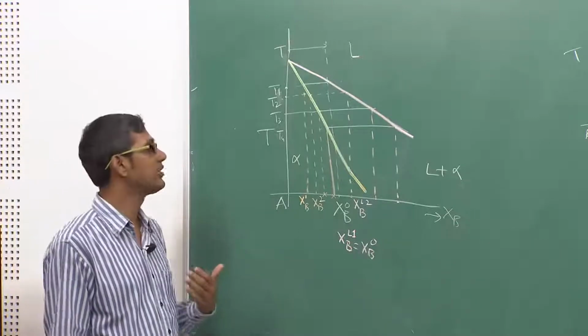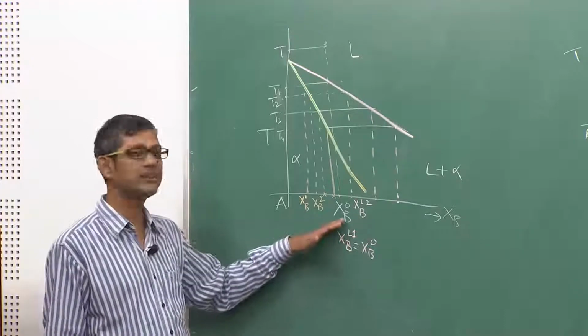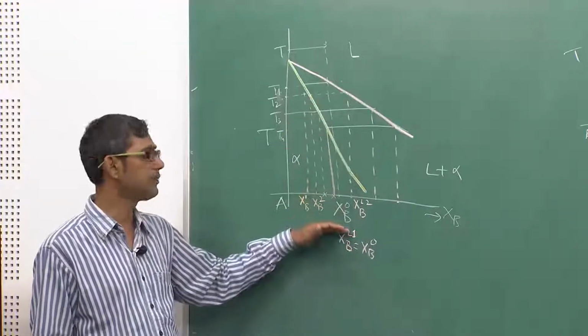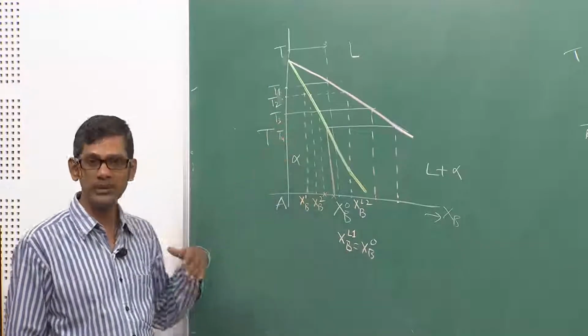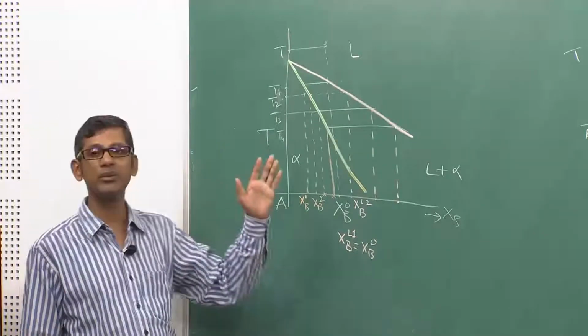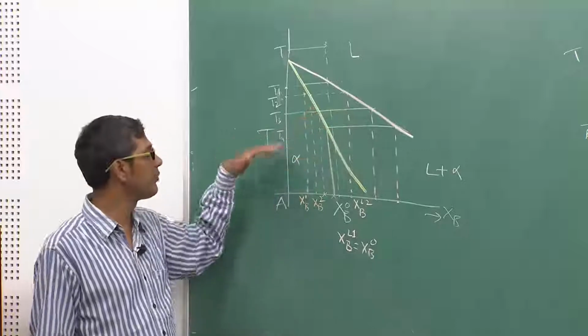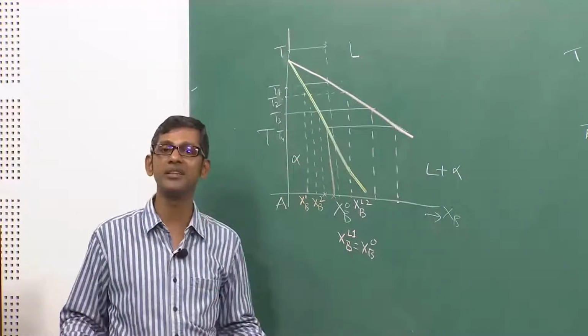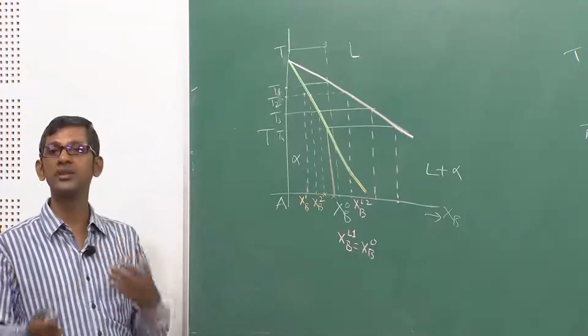So now, if I want to create a solid whose composition is exactly the same as the liquid starting with XB0, I have to keep at every temperature for a very long time for the adjustment of the compositions, because the solid and liquid which are forming at every temperature have different compositions, and these different compositions will lead to inhomogeneity in the solid.